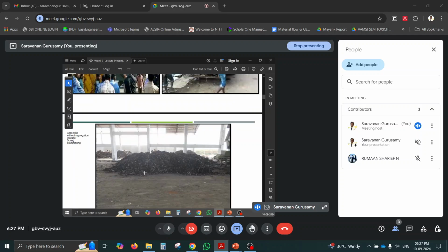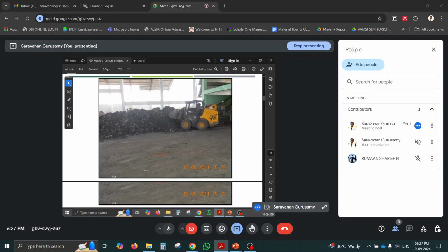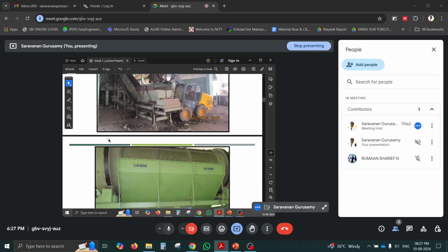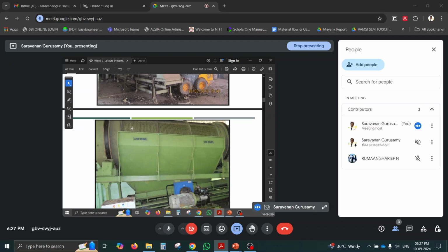First, the unsegregated waste is stored. Then the unsegregated waste will be trommeled. This is the thing I am talking about, the trommel screen. This is a round drum kind of thing. This is not the compost drum. This is the trommel screen. It will have some pores on its surface, like 30 trommel screen, 6 trommel screen, 4 trommel screen. You can see in the next picture. A 35 trommel screen means 3.5 centimeter holes, circular or square holes, will be there. Whenever the feed comes in, the material smaller than 3.5 will fall through this. Sorry, it will be coming through this area.